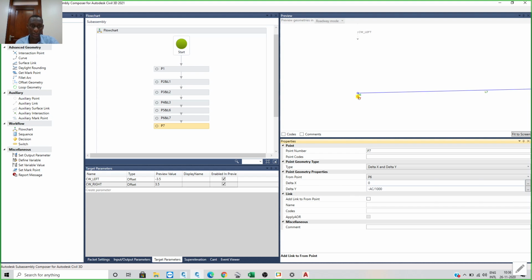And then we can eliminate the link which is joining the 2 points, because after this location, for the AC layer from our typical cross section, after the 3.5 we have a 1.5 meter paved shoulder. So it does not necessitate a link between P6 and P7, because even with the paved shoulder, it will be the same material. So it can have the same shape.